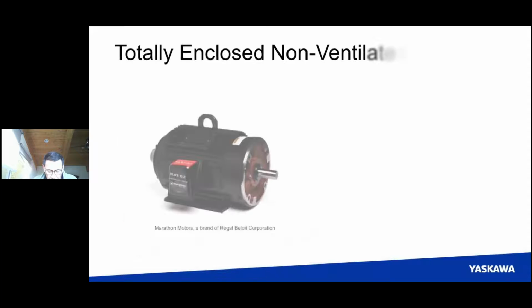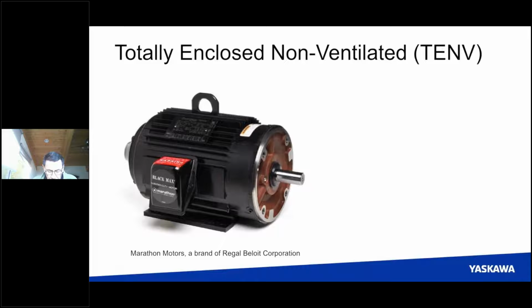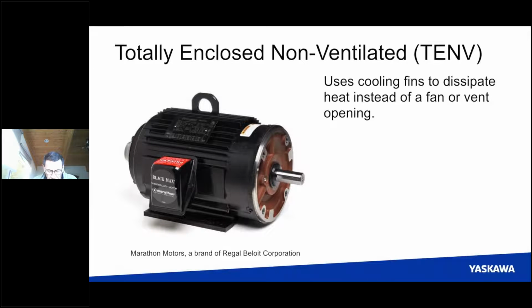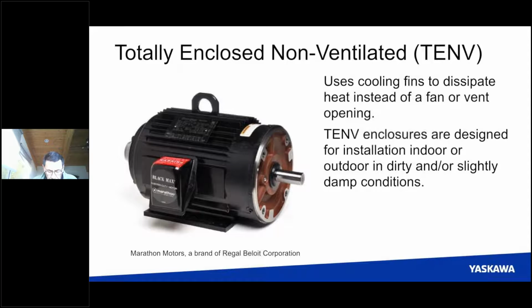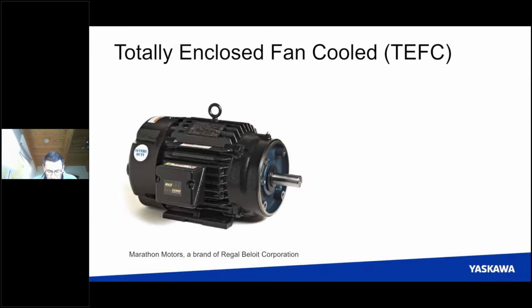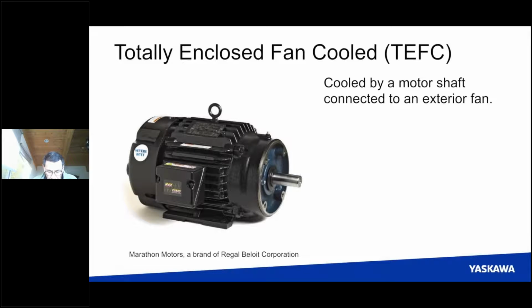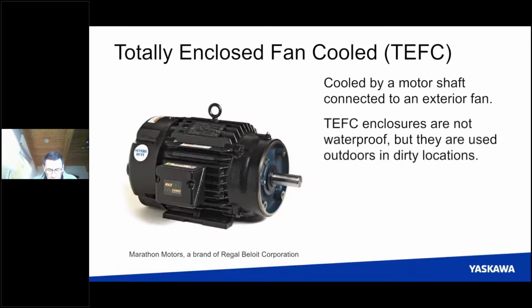A totally enclosed, non-ventilated, or TENV enclosure uses cooling fins to dissipate heat instead of a fan or vent opening. They're designed for installation indoor or outdoor in dirty and or slightly damp conditions. A totally enclosed fan-cooled or TEFC enclosure is cooled by a motor shaft connected to an exterior fan. Though they're not waterproof, TEFC enclosures are used outdoors in dirty locations.